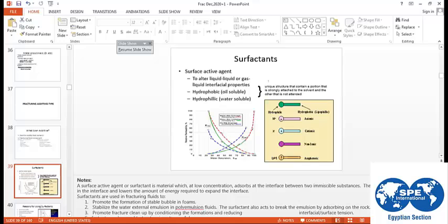And the closure stress can also be calculated as the stress applied from the frac on both sides on the fluid inside the frac itself. However, to start initiating the frac at the beginning, you need higher pressure than the closure. So the fracture gradient is higher than the closure.